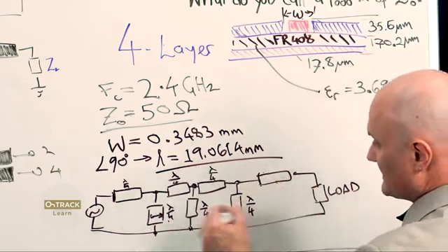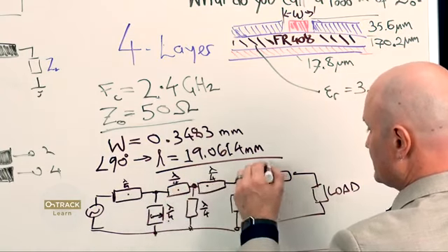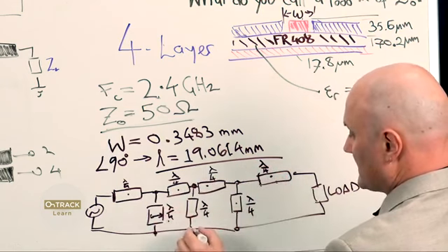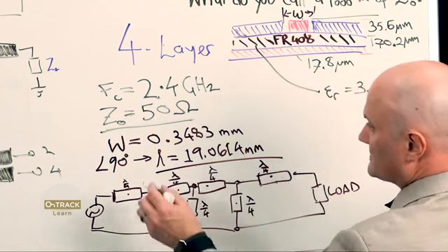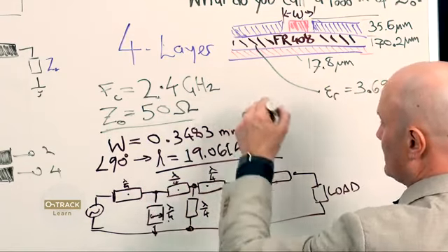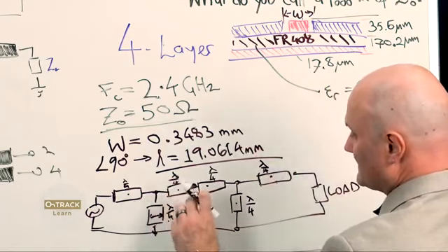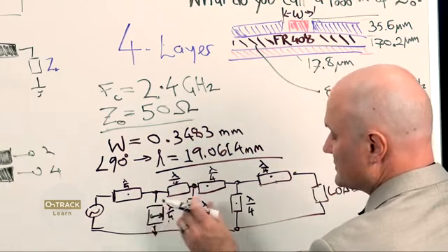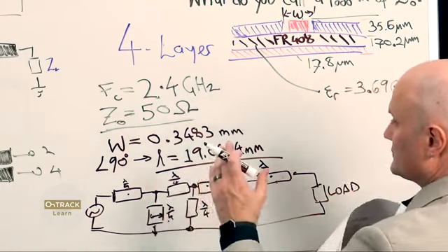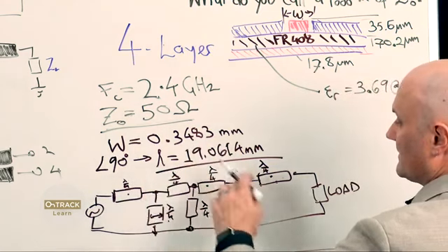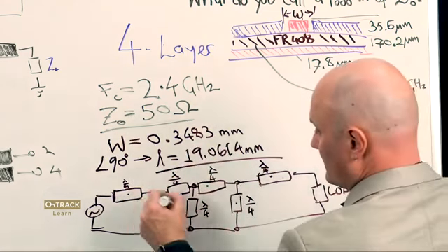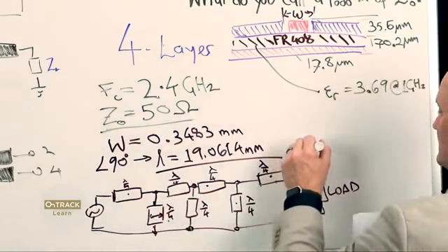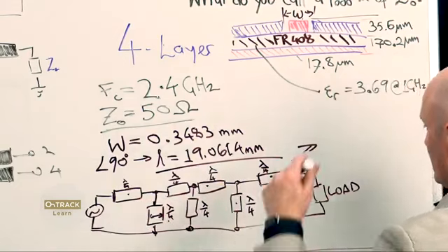And all of this together, 4 series sections and 3 parallel stubs shorted to ground, which each one of these on its own looks like a notch, remember, but we're spacing these out and we're adjusting their widths to change their impedances to broaden the bandwidth.